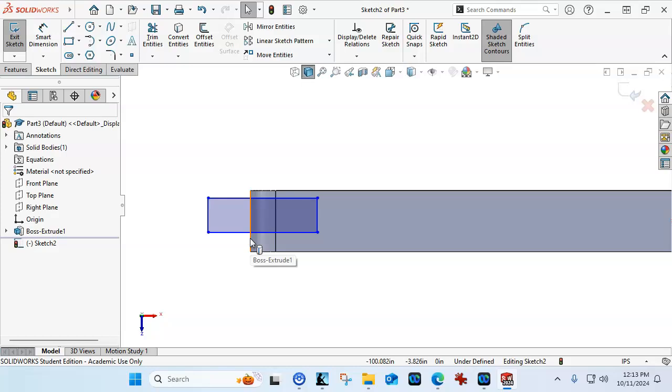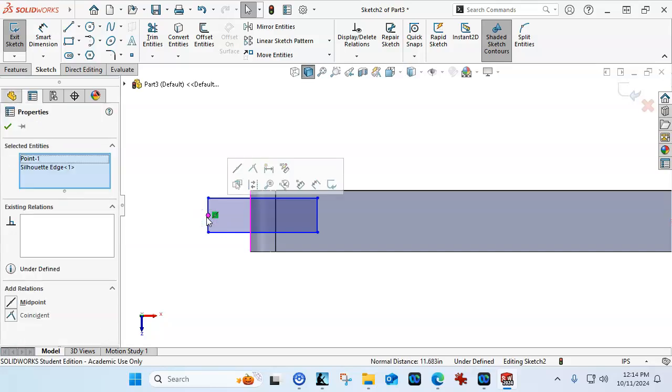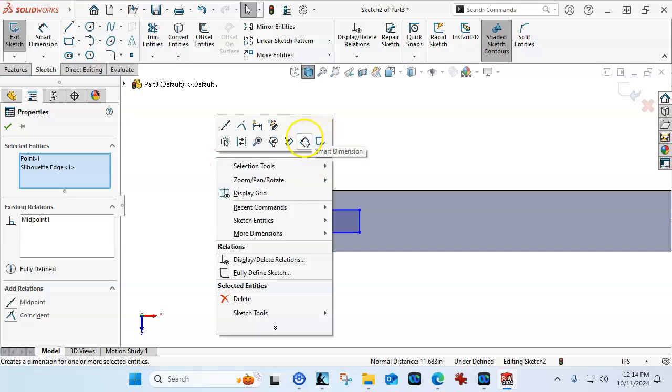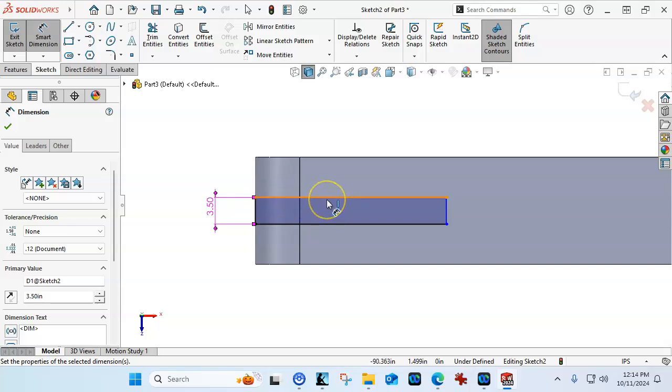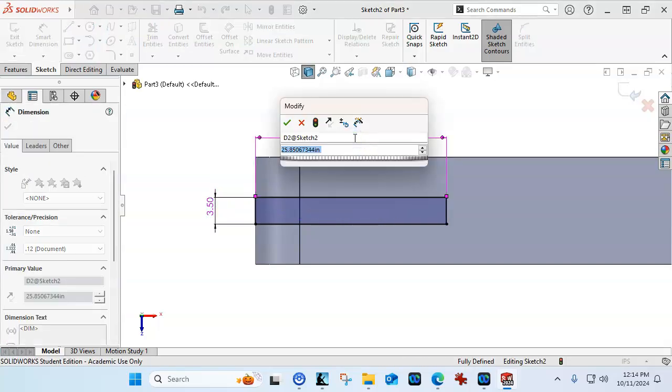So whenever we're dealing with cylindrical, or in this case, the radius or partial cylinder, when we drag along where that plane intersects, even though I'm above it or below it, or on the top plane, I can grab that silhouette edge because where that plane intersects that cylinder, it's going to give me that little symbol of a cylinder with a line through it. So let's see, let me have the midpoint. All right, so midpoint to midpoint. Sometimes that's a little tricky to select. Most of the time I would probably try to get the midpoint first and then come back to the geometry.